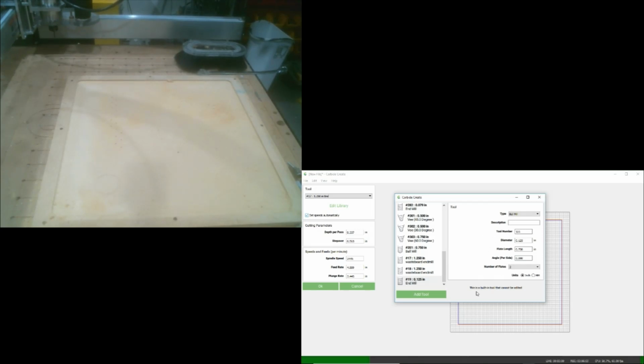edit window will change and this will go away. If it doesn't, you have to left click on it after hitting Edit Tool, and it will get to where we can modify it. You have 3 choices here for end mills: a flat end mill, a ball mill, or a V mill. Ball mill is usually for 3D work or bowl work, and V bit is for V carving. We just want a flat end mill.